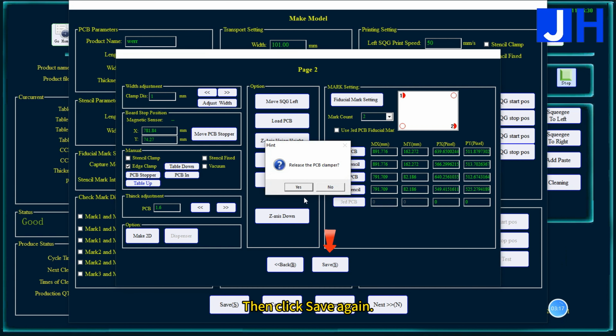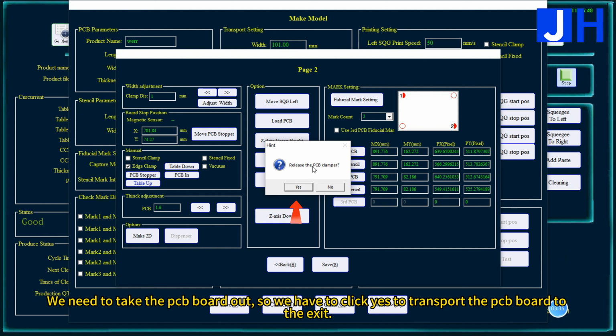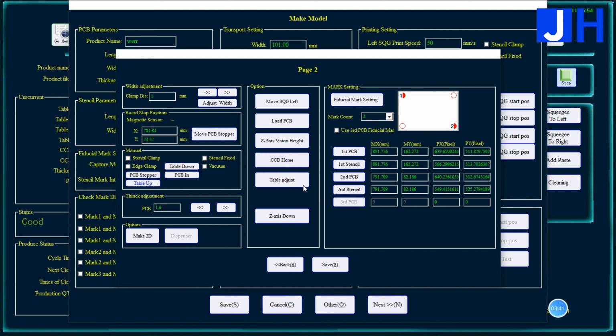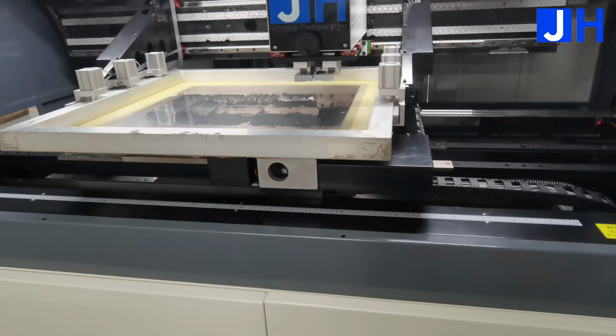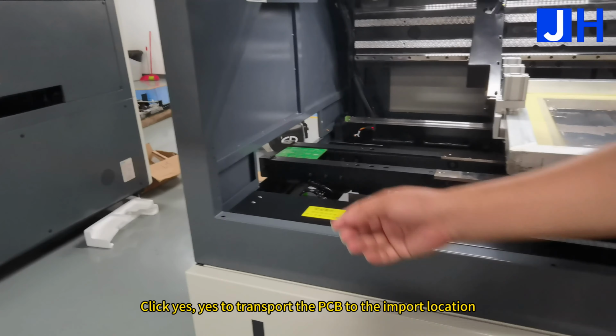Then click Save again. The machine pops up and asks if you have released the PCB board. Click Yes, which means to transport the PCB board to the exit of the printer. If you click No, the printer starts working directly. We need to take the PCB board out, so we have to click Yes to transport the PCB board to the exit. Click Yes to transport the PCB to the import location.